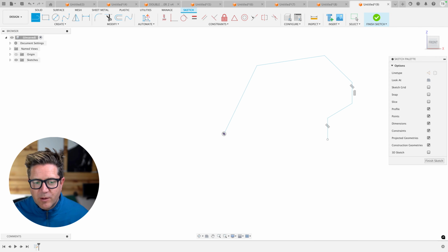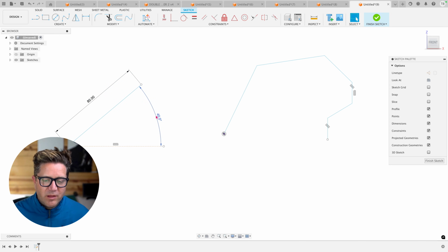You'll notice that when you are sketching a line, it's automatically allowing you to place a length value. Type in that length, hit tab. You can also apply an angled value here. And so you've got a dimensioned line with these 2 dimensions already applied.